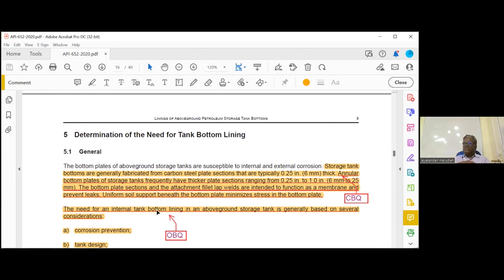That is half of the 0.1 inch, 0.05 inch allowed. That is the advantage. That means you can increase the inspection interval, because 0.1 inch is coming in 10 years, and when it becomes 0.05, it is 20 years. Double. So you can increase the interval. That is the advantage of going for a thick film lining.